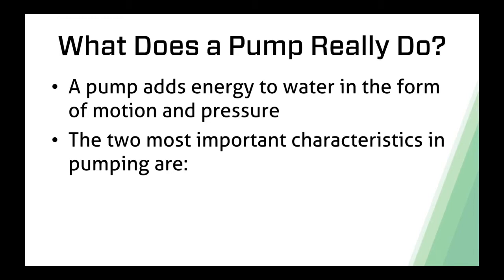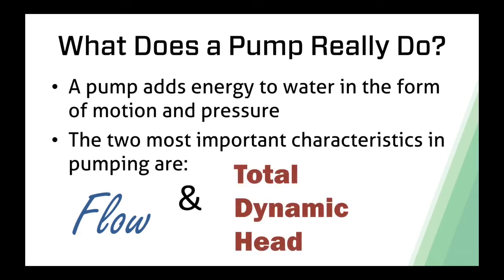So in pump selection or pump sizing, the two most important characteristics that we are going to try to determine and subsequently use are flow or flow rate and total dynamic head. And I'll cover these terms here in the next slide or two. Total dynamic head is also very often abbreviated just as TDH.